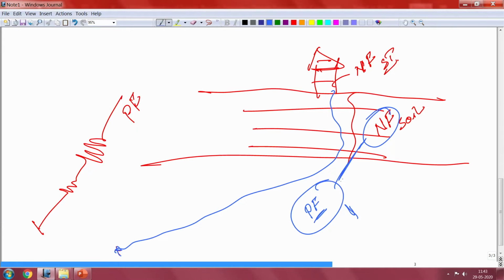Or, if this combined frequency reaches a structure with a frequency close to it, the structure will have the maximum response and failure. So, when designing, we should see that the natural frequency of the soil column does not go close to the natural frequency of the input motion expected in the region, and even the combined frequency of these two should not match your structural frequency.